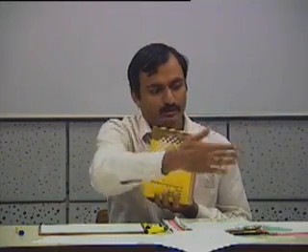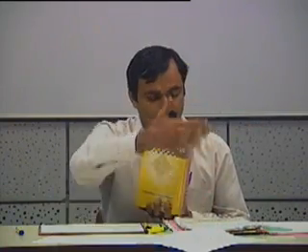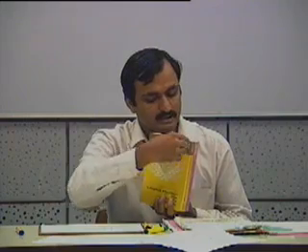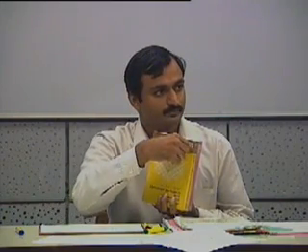Say from your point you take a projecting plane which is parallel like this, and the block is at an angle. In that case you will not find the edges of this block to be parallel. But if my blocks are like this and the plane is also parallel to it, then these edges will appear parallel, and their intersection would seem to be at infinity. That is why I said if my projecting plane is parallel to these lines, then there will be no vanishing point.